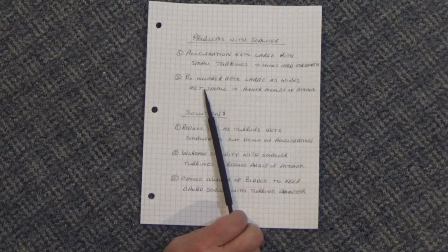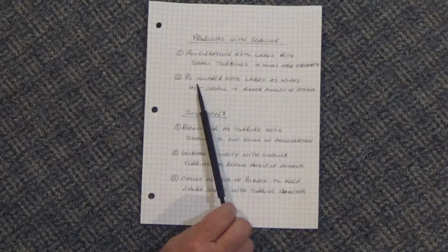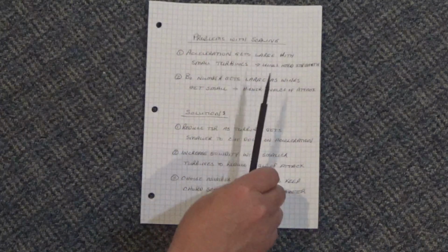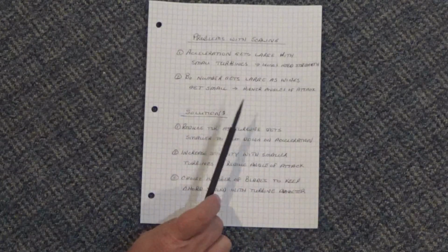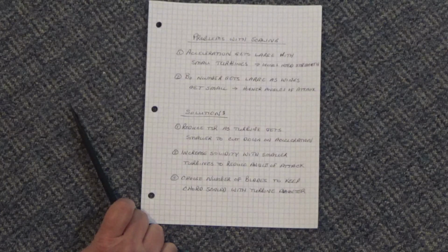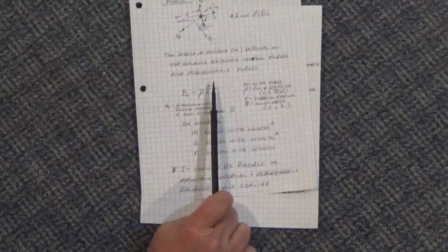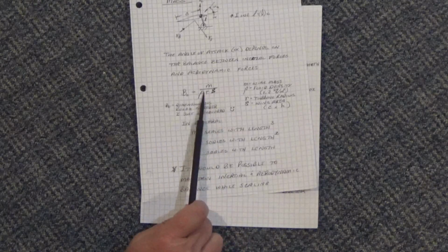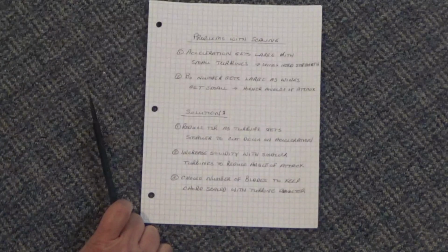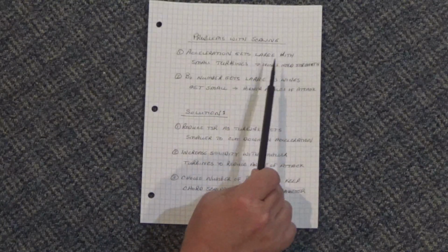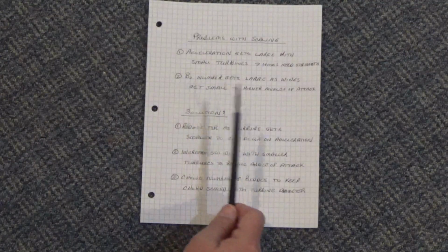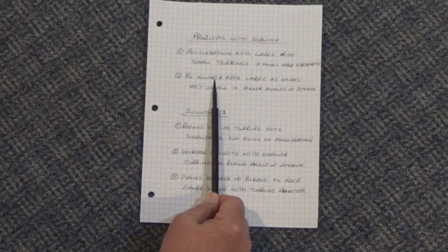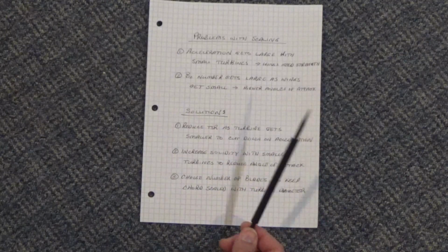And also, what I've been finding is that this dimensionless number that should be the same as you go up and down, it tends to get higher with the small turbines. Maybe the mass per unit area of wing stays the same, but then you've got this R term in the denominator, and so because the acceleration gets large, the dynamic forces get higher relative to the aerodynamic forces, or the inertial forces get high relative to aerodynamic forces.